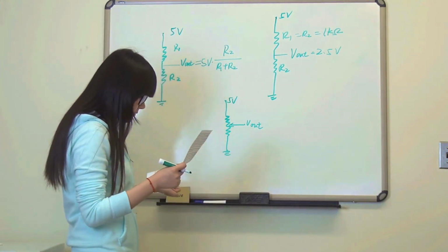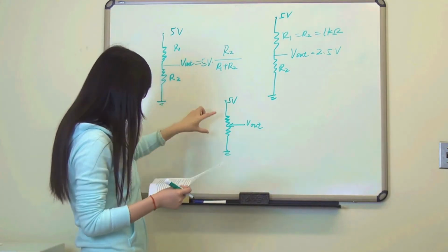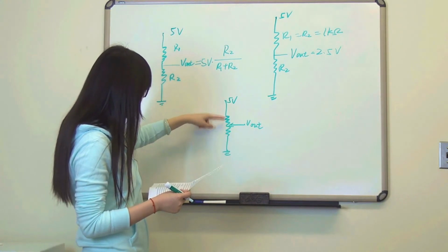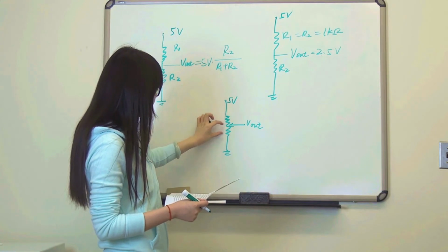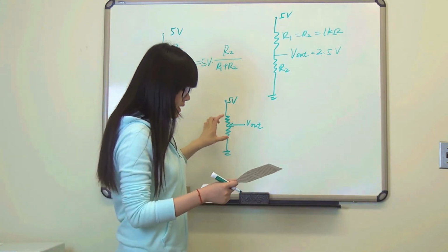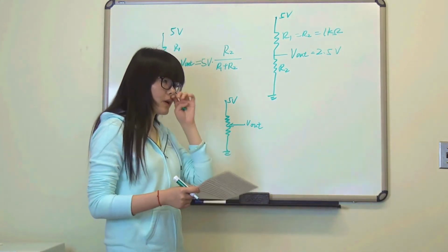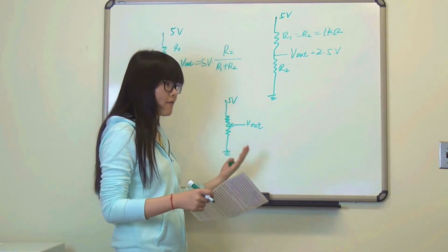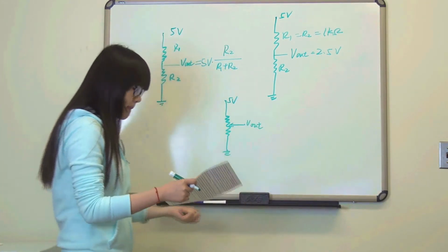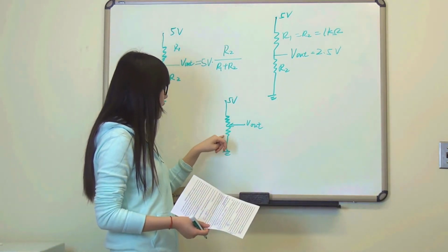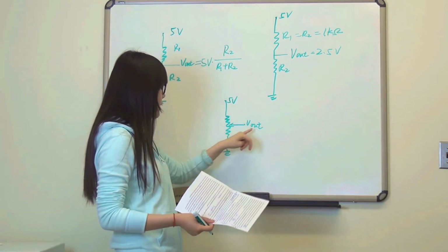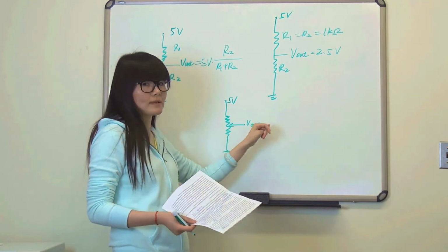When the wiper goes up and down, it changes the resistance of the top and the bottom. In this way, it essentially gives you a voltage selector, and you can feed it into the Arduino pins. So if the wiper is stopped at the bottom, it will connect to the ground, and the V out will be 0.